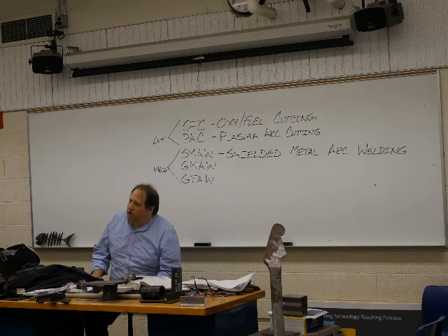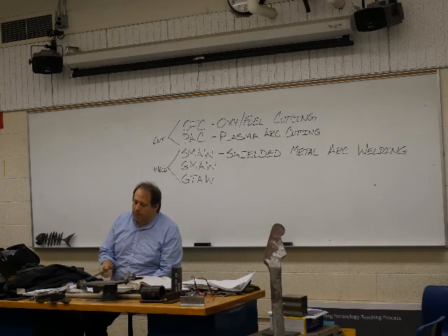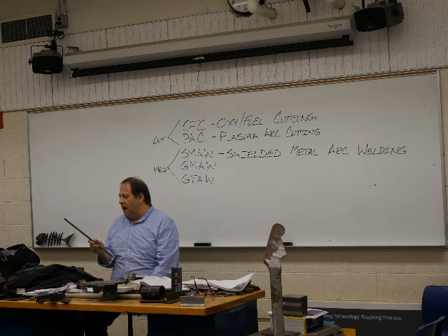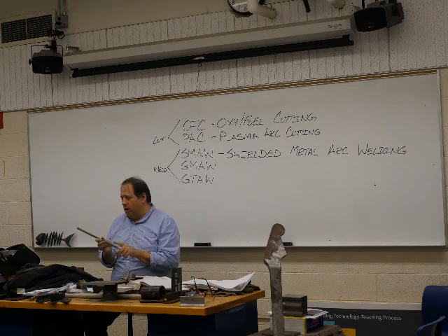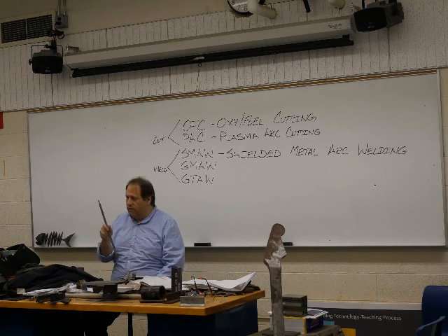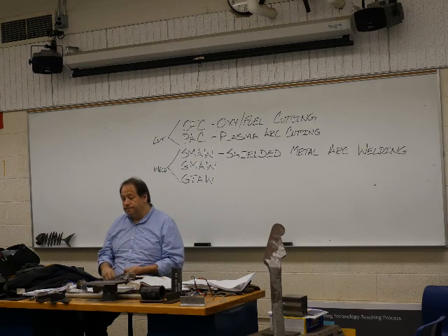This is kind of the game changer. This is what made this process much, much better. There's a couple things this also does. If there's any kind of additives like alloys, it's going to be in powder form here. It's not going to be in the metal part because we basically got a steelmaking furnace sitting in front of us as everything melts together. So it just kind of melts out of the flux.